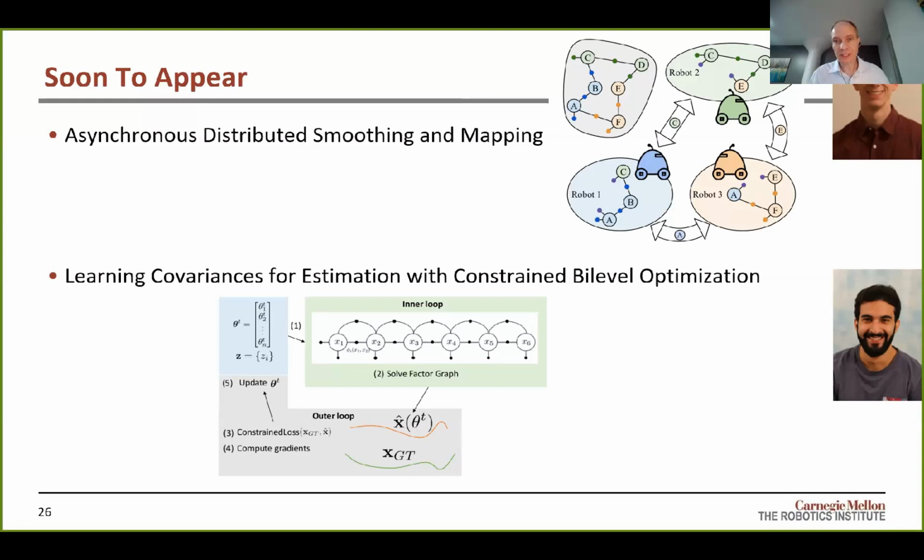Which sensor specifically? 4D radar sensor. Oh, yeah. So it's typically currently a compromise, right? For the TI radar, they decided to put most of the antennas in the bearing direction to get as high resolution as possible. It's equally possible to distribute these antennas equally. So you're basically losing some spatial resolution in bearing, but you gain the resolution in elevation.